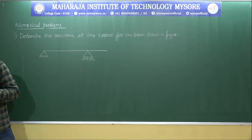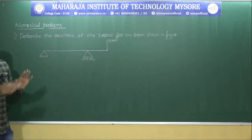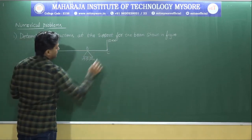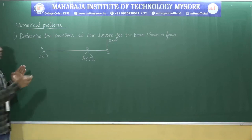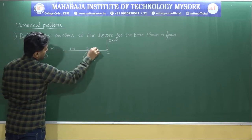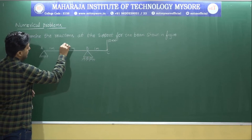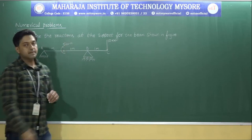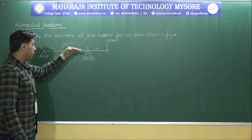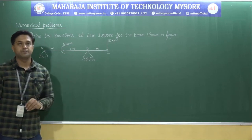Now the loading condition that they have given is 10 kilonewton, which is acting at this particular junction. They have given this as A, this as B, and the next point as C. Next they have given 1 meter, so they have considered a point here. This is 1 meter, this is 1 meter, and this is 1 meter. They have given a pure moment there, that is 5 kilonewton meter. So this is the diagram that they have given. This is the beam. We are applying the load onto the beam, so that load needs to be taken care of by the supports. Yes or no? So we need to calculate the support reactions.